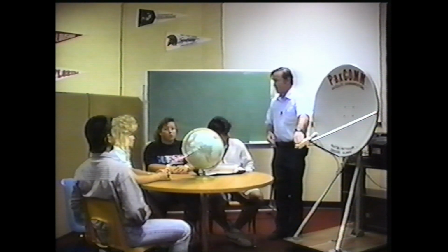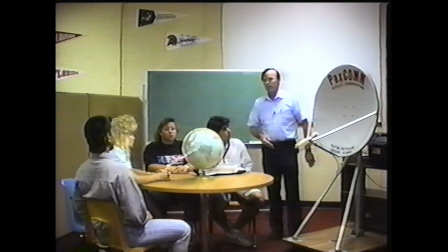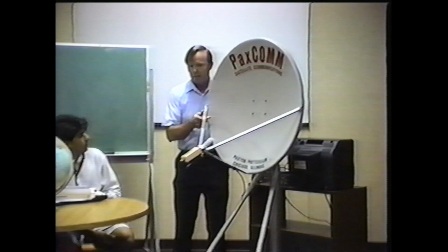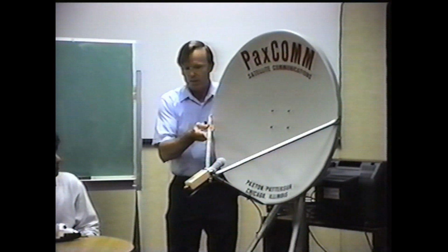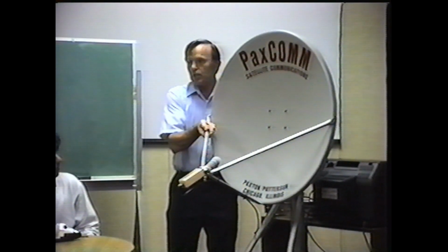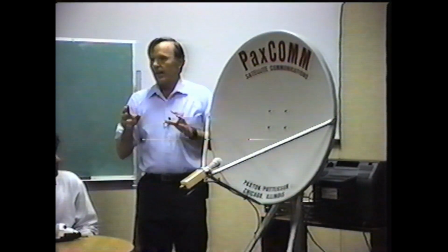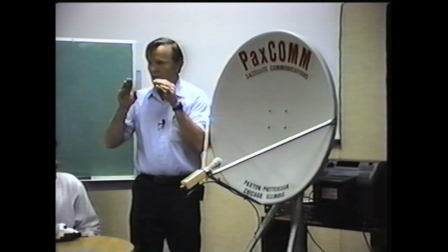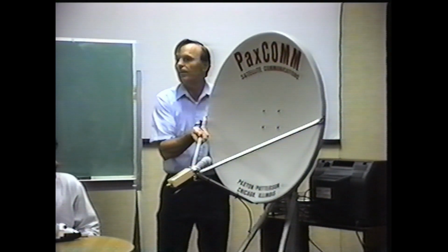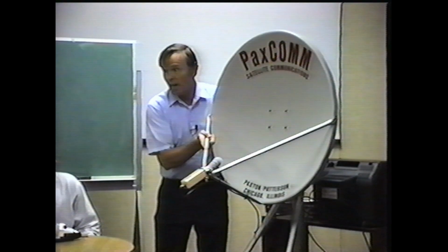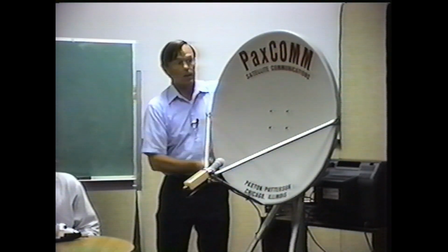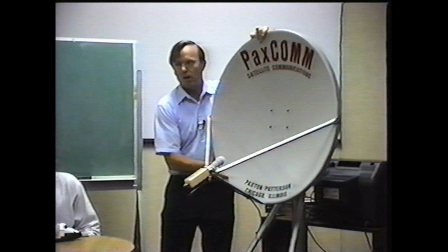Another question? Yeah, how much can you move the dish and still get the picture? Oh, if I'm watching a television picture, and I move this dish this much, we've lost the picture. That satellite is positioned over the Clarke belt, and the antennas are so directional that if I move 1 inch in any direction, I've completely lost the signal. That's the reason you have to be careful when you set up and aim the system. If I raise and lower it that much, we've lost the signal.